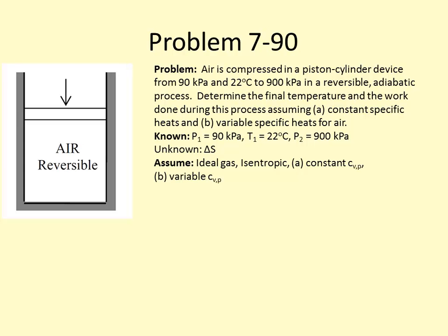Using the approximate analysis where we assume that the specific heat varies linearly, so we can take just some constant average value in the middle. Okay, the second method for an isentropic process is we can either use our reduced pressures or our reference entropies to find our final values.